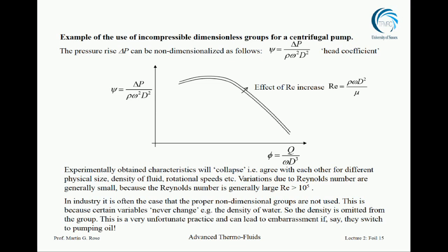Now this is a feature of all compressors and pumps, that they become unstable at low flow rates. And it's a very important part of the technology of gas turbines. I'll talk to you more about that in a subsequent lecture. But just be aware that low flow is a problem. Turbines don't care. They'll work over the complete range because they're stable. Compressors and pumps fall over when the flow rate is too low.